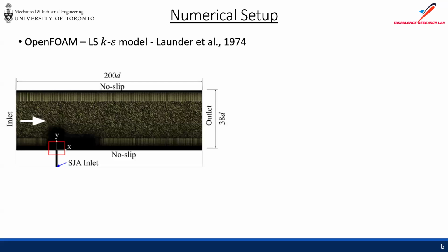We've decided to attach the circular SJA to a duct crossflow rather than an airfoil for two reasons. First, we're trying to analyze the fundamental physics and especially the structures of the SJA without the added complexity of the airfoil crossflow. And second, for the Reynolds number of the airfoil that we're working with, we have a laminar separation and transition to turbulence.